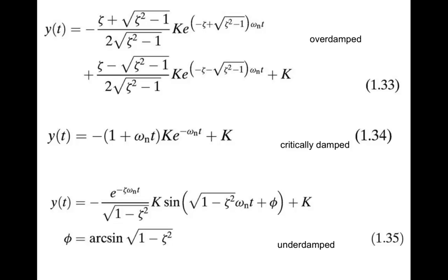So as you might remember from differential equations, all second order differential equations that are linear fall into this category where you have a second order algebraic equation if you do a Laplace transform, and then when you solve that quadratic, you can have a real, an imaginary, or a complex solution. Or you can have a double root. Now, we're not considering the imaginary solution because that would be a case where you had no friction, which doesn't really happen in the real world in a mass spring problem. So we would consider only the complex and the real root.